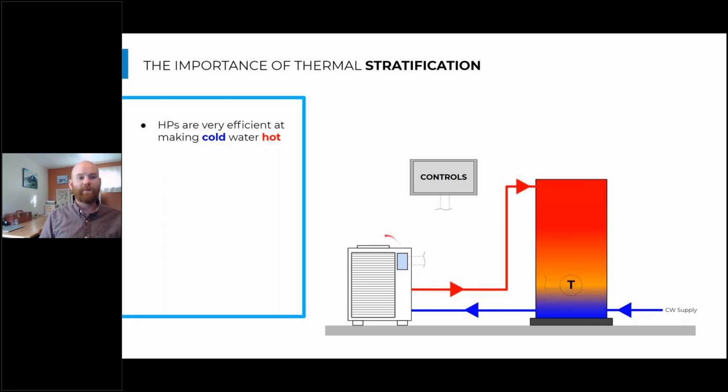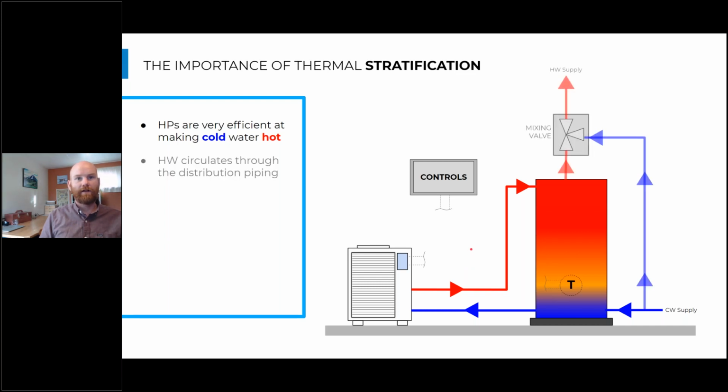Once again, the heat pump is operating in a heating cycle, and so this is a very reliable point for that heating cycle to be operated and tuned to. And we send this hot water out through the mixing valve, which is often taking 140-degree water in our storage tanks, tempering it down to 120-degree water going out to those end-use fixtures with some amount of cold water to get that tempering effect.